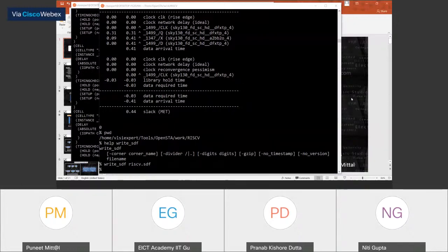You are using that netlist as it is, and you're not going to change this portion of your design. So you use the SDF of that block and give it to the tool, so you're not going to spend time calculating the delay values of that block. I hope, Naveen, I answered your question.